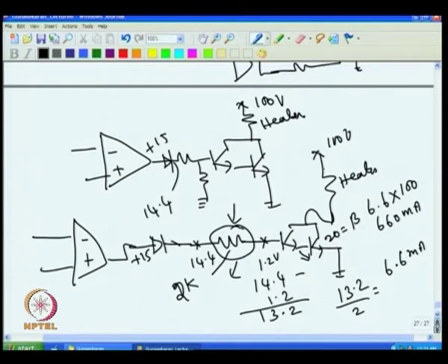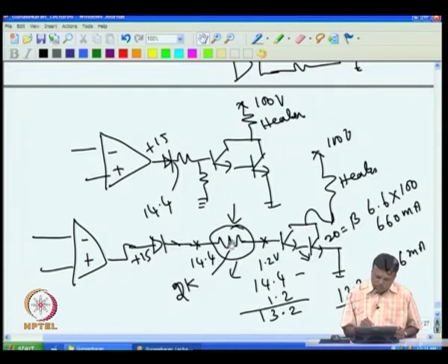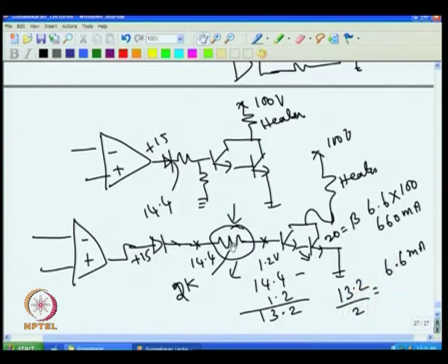If 13 ampere current cannot go and is limited by the resistance, then whatever current can flow, it will flow. So, up to 13 ampere current can go through this if I use this. So, the transistor will not get destroyed if I put this resistance. If I want more current, say 20 ampere through this, then I should reduce this resistance such that I will get 20 ampere current through this.